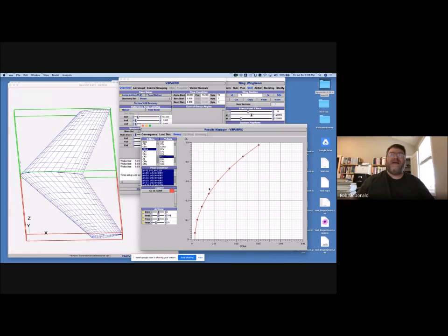What you need to do, and this balances a lot of different things in aircraft design, is get an estimate of the weight of your aircraft. Let's say you think you can come in at 35 pounds, with all your structure and all your sensors and all your batteries and everything else. Then you need to figure out what area the wing needs to be. To make the math easy, let's say it's 10 square feet. So at 35 pounds and 10 square feet of area, you have a wing loading, which is just that ratio, of 3.5 PSF, 3.5 pounds per square foot.